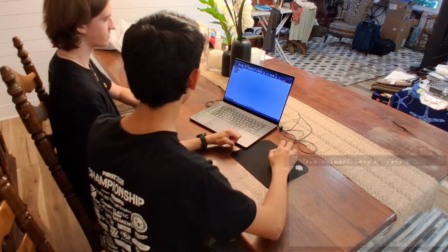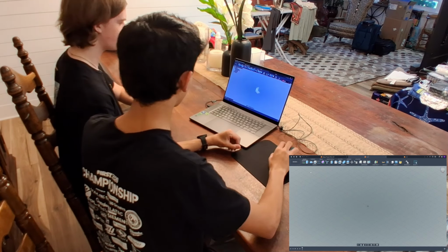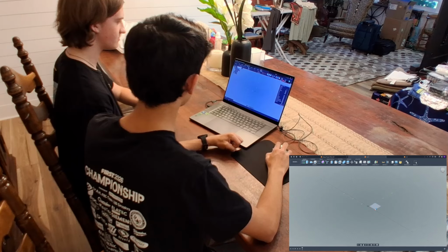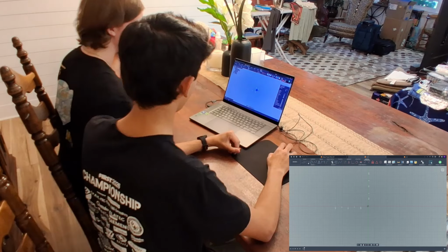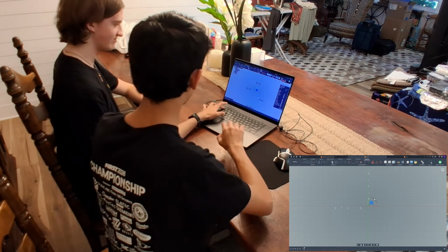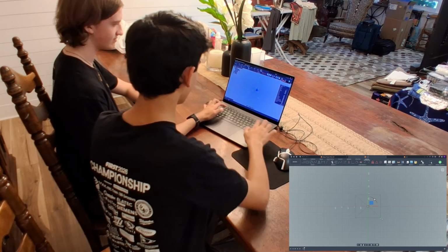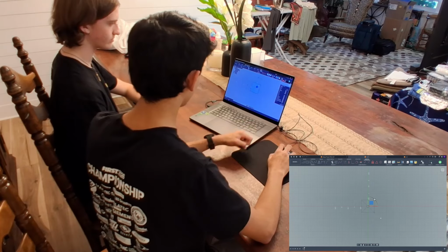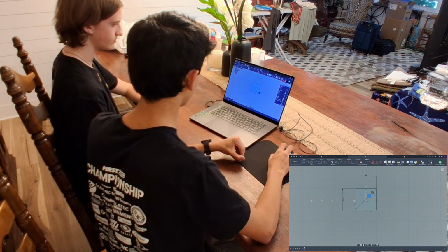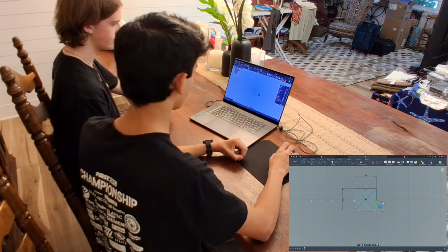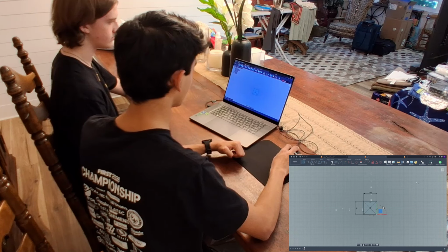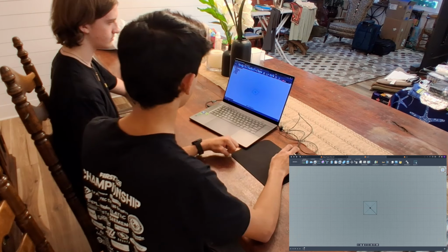First things first, we have to start our sketch, and then we're going to start with the center rectangle, and just make a square 1 inch by 1 inch. Then from there, we're just going to put a little diagonal line over from the center, and that'll be helpful later. So I just want you to go ahead and try to do that.